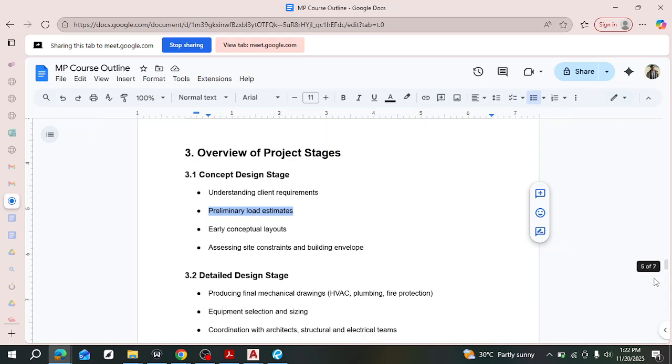The purpose of this rule of thumb is that it's faster and helps in case you need to just look at the project and do the little math in your head. So this is what you use. If the space is bigger, you can always get the floor area and then do this, and you can have an idea of the amount of CFM needed for that space.